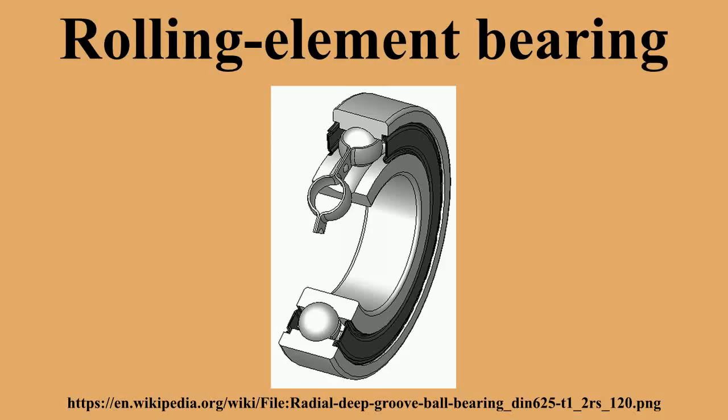Rolling element bearings have the advantage of a good trade-off between cost, size, weight, carrying capacity, durability, accuracy, friction, and so on. Other bearing designs are often better on one specific attribute, but worse in most other attributes. Although fluid bearings can sometimes simultaneously outperform on carrying capacity, durability, accuracy, friction, rotation rate, and sometimes cost. Only plain bearings are used as widely as rolling element bearings.